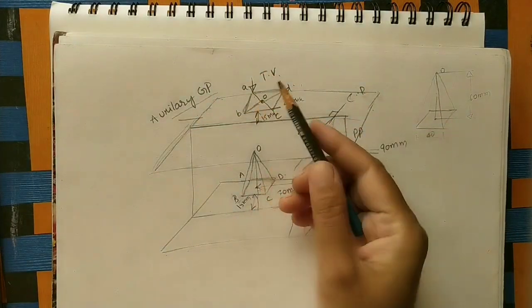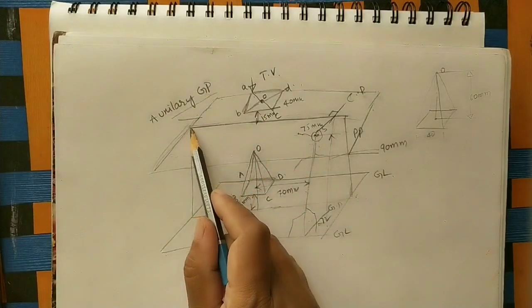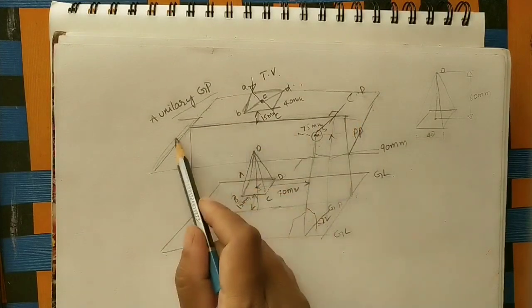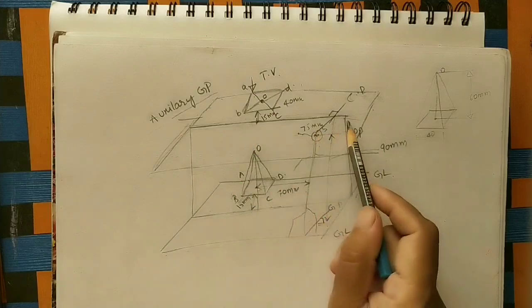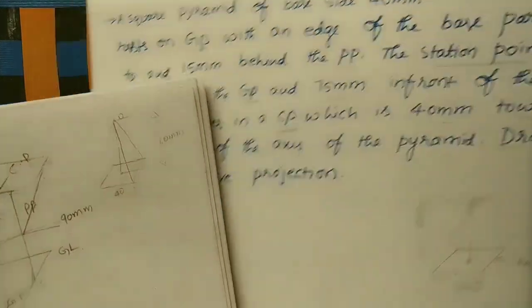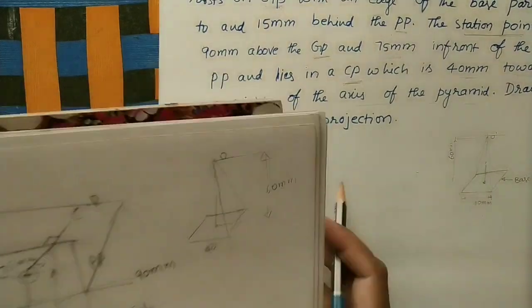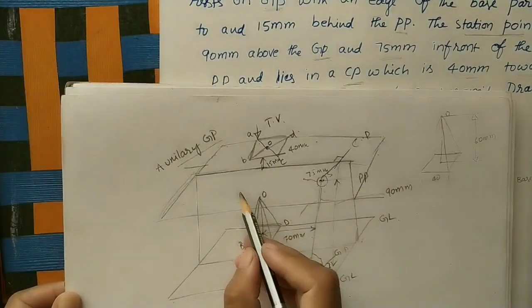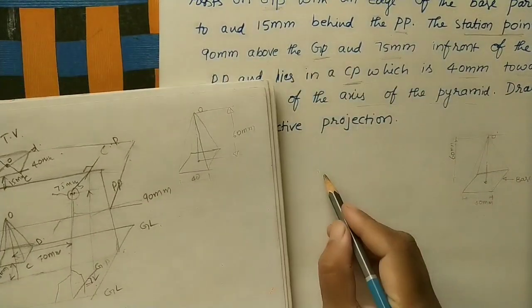If we are tilting like this, initially we can see this line here. We need to draw this line. Which line is it? It is the picture plane line. Initially draw the picture plane line. Roughly I will draw it, and after that we will use drawing instruments. First we need to draw this picture plane line like this.